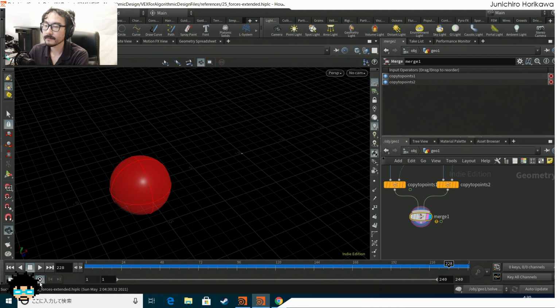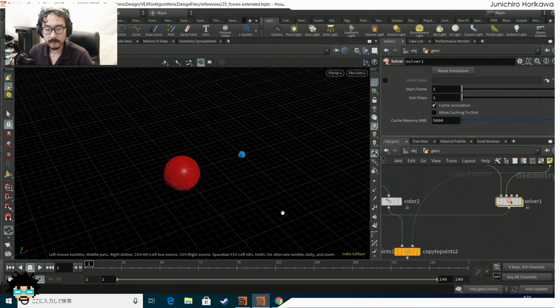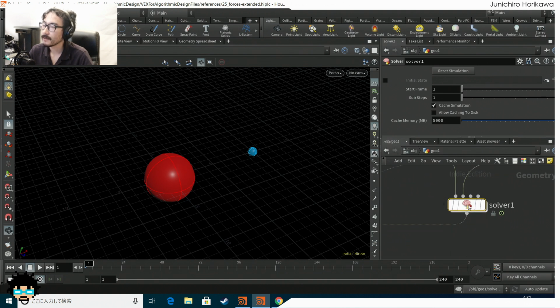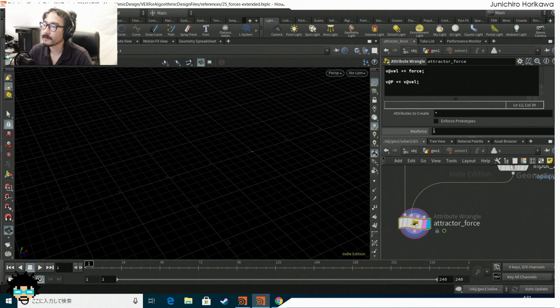As you can see, it's a bit too fast and it looks like it's bouncing. So let's try to fix this one. One of the reasons I could think of that was causing the bouncy or too fast movement is the maximum value for this force value. So let's decrease this value to, let's say, 0.2.